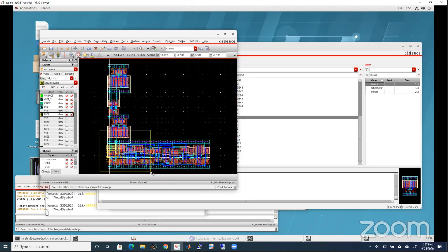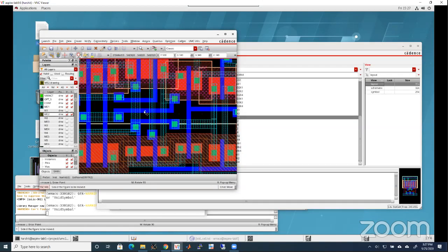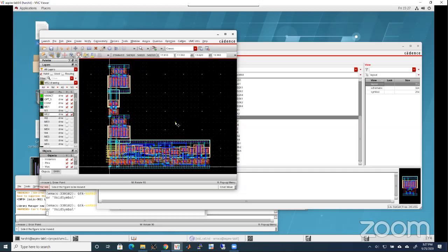Okay, so first of all, that is there. Now, the NMOS is half the size of the PMOS. That means the space between the ground and power rails has to be divided: 1/3 of it is given to the NMOS, NMOS is here, and 2/3 is given to the PMOS for layout. Use only metal 1 and poly for all interconnections. Do not use higher layer metals, as much as possible.